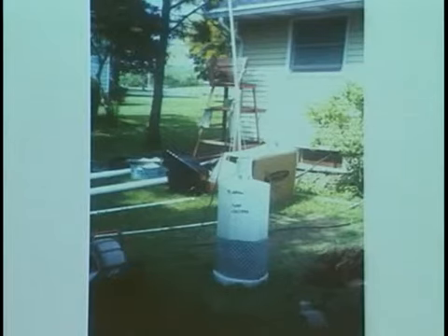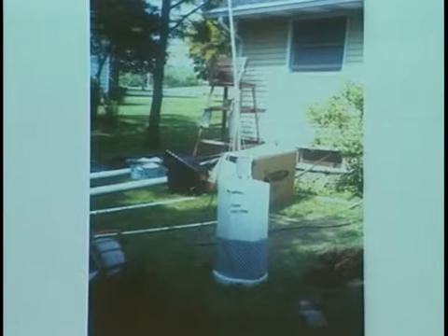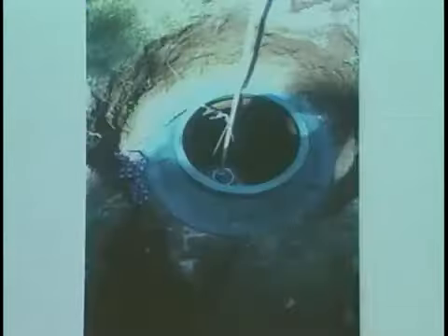Now, for these to work, number one, the tank's got to be the proper size. Number two, it has to be demonstrated that the system did work before it failed. In other words, if it was an improperly designed, improperly installed system, like in clay soil, this isn't going to make it work. It had to have been a system that did work for a number of years before it did fail. So these units go in the existing septic tank.